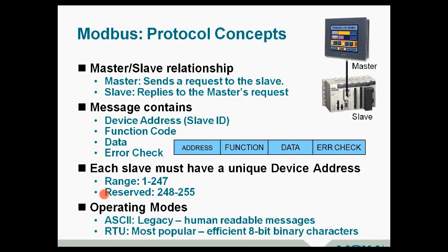And lastly on this, while it's not used very much anymore, there was an early standard called Modbus ASCII. It is very rarely used anymore, and if it is, it's quickly being replaced by Modbus RTU. It utilized an easier to read format that was not as compact as the current standard. RTU stands for Remote Terminal Unit. It's the most popular. It uses a binary address and data format that's more compact, meaning that it takes less resources to send the message, and you can get a faster polling cycle and see updates a lot quicker.